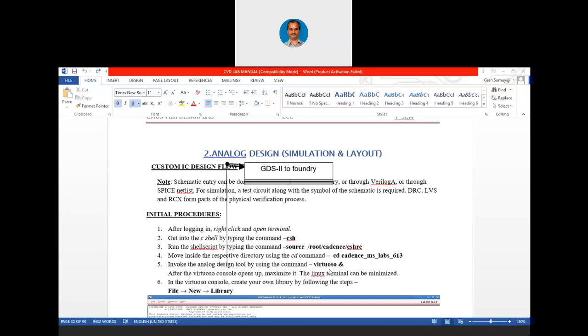Virtuoso also has to come into the picture. Now, if you don't give the symbol ampersand, Virtuoso will open up, and at that time it will hide the terminal. If it hides the terminal, you will not have any access to the commands. When you don't have access to the commands, you will not be able to know what is actually happening in the background. If you have to correct something, you will not be able to correct it when the terminal is not accessible to you.